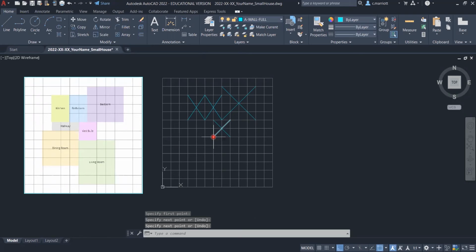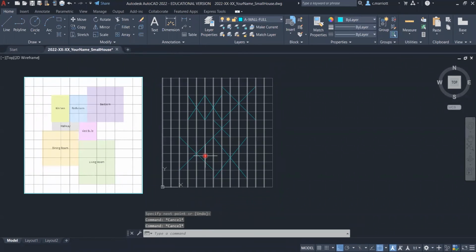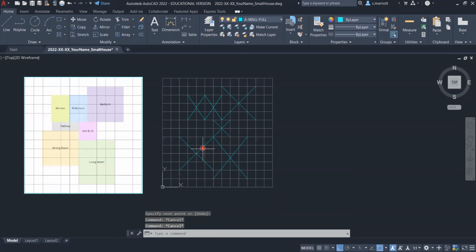And you'll notice that I have ortho set, but the object snaps are kind of overriding. One thing you'll notice is that every time I choose a point, it's finding either an endpoint or an intersection. The little green X that you see is an intersection. Okay, so something I did incorrectly here. I'm going to move my dining room up. So M for move. I picked both lines, and I'm going to reset these to one grid up, right?